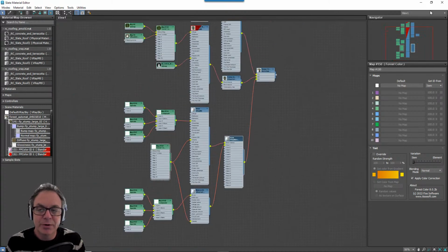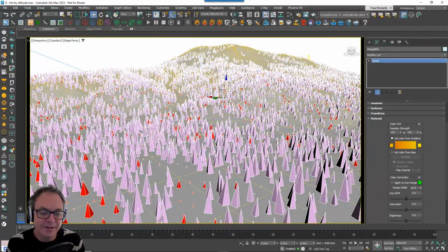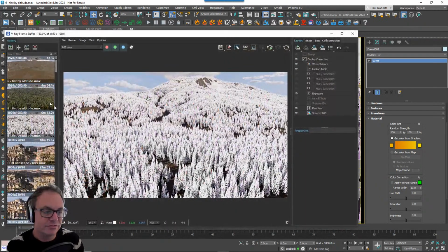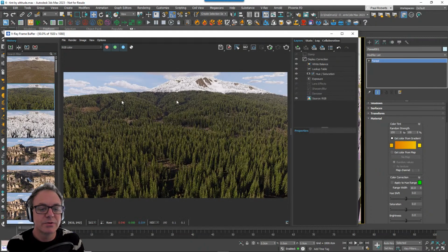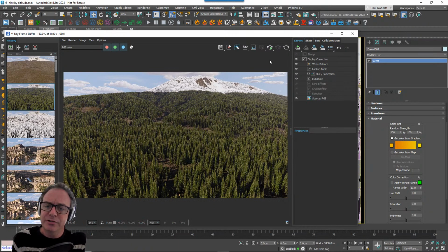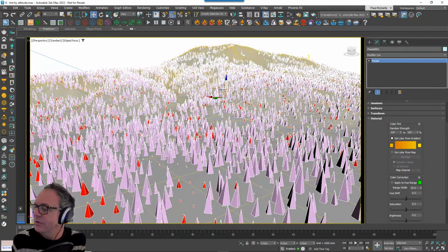And then if I were to render that now, basically because of that, I'd have removed the snow up until the snow line. I won't render it because it will kill my stream, but it will look something like this, which is just a very hard line at the moment, but it does illustrate how it would work quite nicely. Okay, so basically below this line, I've used that mask to remove the snow, which is quite straightforward. It's quite a handy effect. There's loads of useful forest effects in there, and we're going to be adding more because we've added some improvements to forest effects in Forest Pack 8. You can see that in the list of changes on the forum.